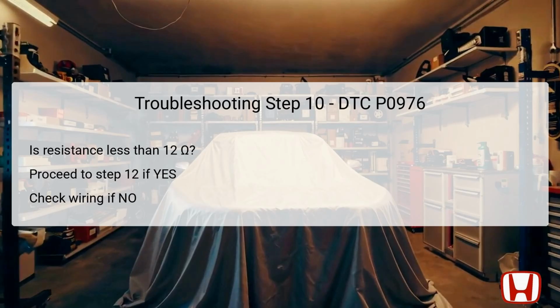This could lead to either a poor connection, a break in the wire, or other faults that would impede proper electrical flow, necessitating additional troubleshooting of the wiring harness. Identifying resistance levels is crucial for diagnosing the health of the electrical components involved in the shift solenoid circuit.